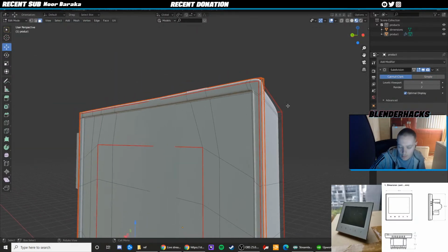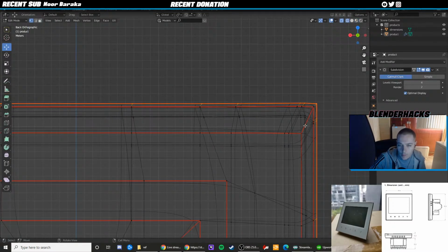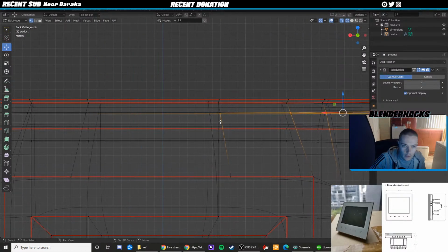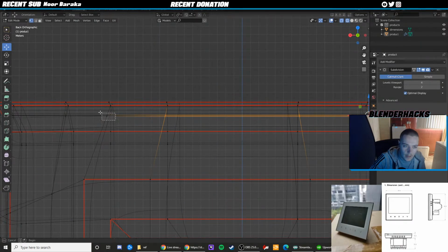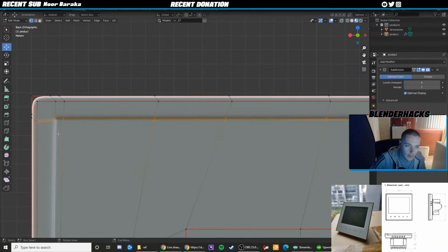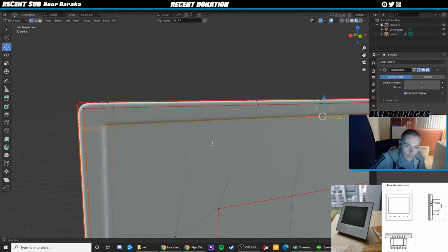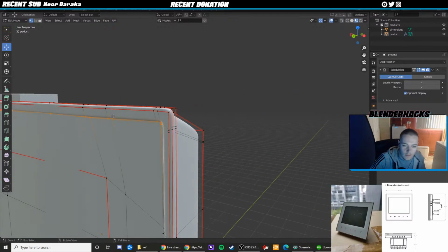So as you can see now, if I go 1 for the front view, swap it around. This top panel or extrusion we have going on, I guess it's more of a border we call it, it's too big. We're going to go into wireframe mode, select all these vertices from here. We want these ones too. You want to make sure you take time when you're selecting vertices.